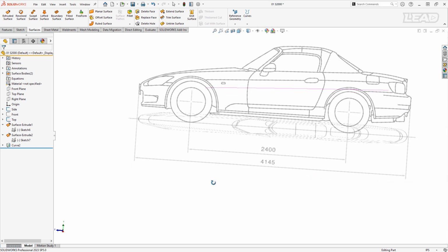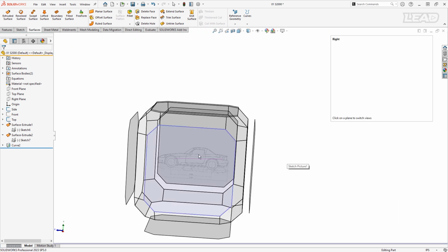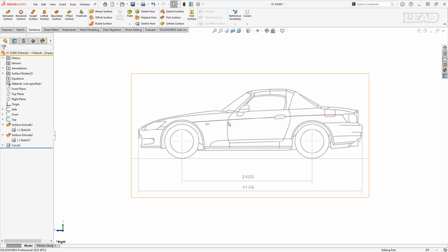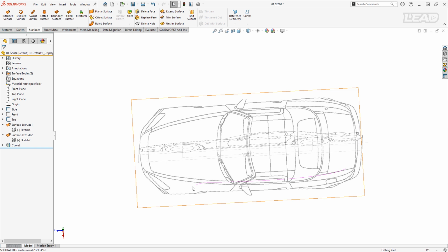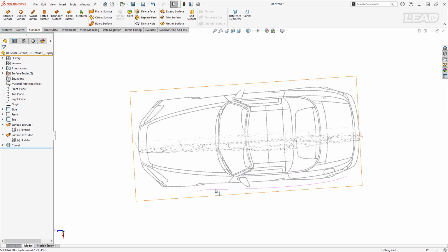Now, a couple of tips for you. If you are going to carry on building more curves off of this, then you do want to make sure you still use convert entities and you make sure that the endpoints are in the same location. I would say that if you're having more than one change in curvature direction, to break it up into multiple curves. So in this case, from the top down, we had that inflection point going inward, and then it changed. So it went from convex to concave. I think that's perfectly fine. If it were to change directions again, then normally what I would do is break that into two separate curves and ultimately create two separate surfaces from it.